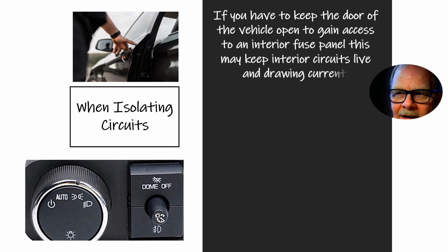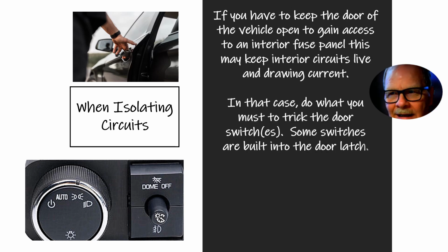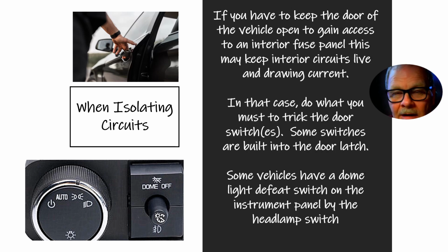Now, if you got to keep the door of a vehicle open to gain access to an interior fuse panel, and by the way, remember, some of the fuse panels are under the back seat, some of the fuse panels are in the trunk. Some vehicles will have fuse panels on the left and on the right, or on the left and under the seat. And GM cars are like that, and some of your other cars are too. Make doggone sure you know where all the fuse panels are. Some of the Chrysler, Dodge Chargers and stuff, like an 08 Dodge Charger's got a fuse panel in the trunk and all that. So make sure you know where all the fuse panels are.